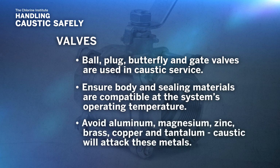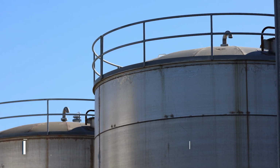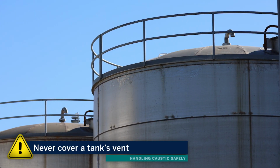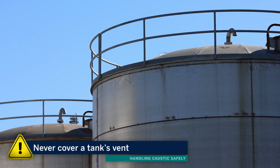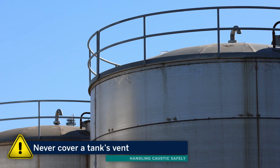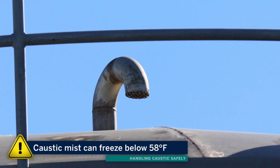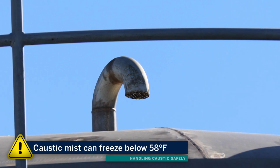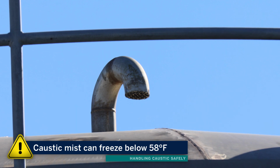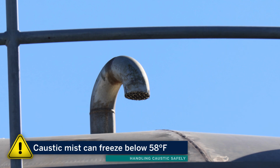Aluminum, magnesium, zinc, brass, copper, and tantalum are materials that are attacked by caustic and must be avoided. Caustic tanks are normally vented to atmosphere. Never cover a vent used to protect against tank failure due to overpressure or vacuum. Ensure that the vent size is appropriate for the tank's operation. Liquid caustic can sometimes freeze in and plug tank vents, where mist carryover exists in climates below 58 degrees Fahrenheit. Ensure tank vents are maintained clear from restrictions due to caustic buildup.